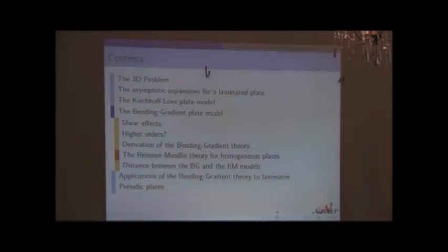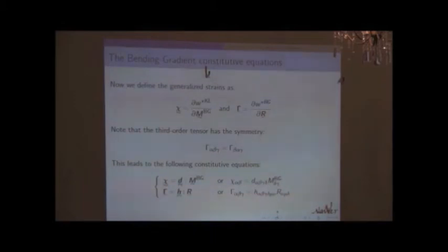Okay? And the very reason, I mean, there are several ways of understanding that, but one reason is that I say that the transverse shear compliance tensor, this guy, H, is positive, but not always positive definite, so it has some zero.